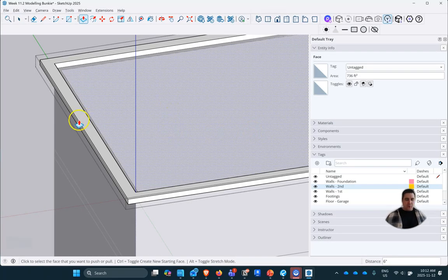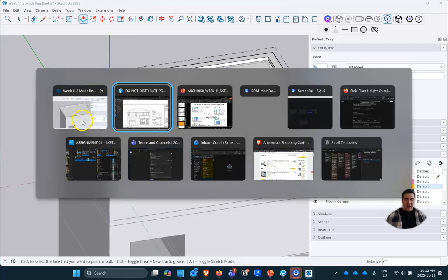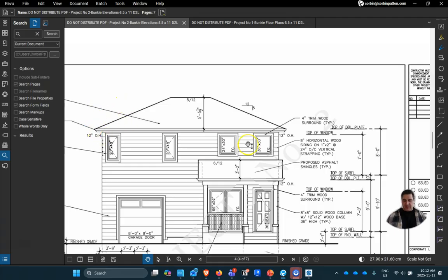So with our roof here, we're going to go up 6 inches. That's roughly our fascia board. So you can see that we have one on here. You can see that there's like an eaves trough or something there, but we don't know. There's no dimension there. So we're going to call it 6 inches. We're just going to assume that that's the case.